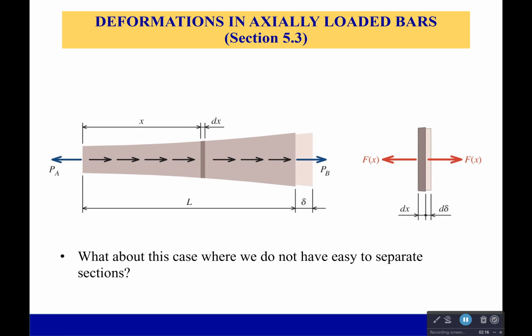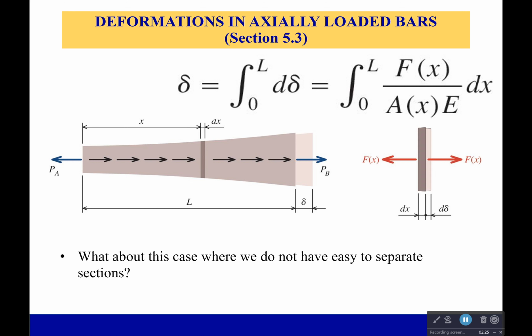In cases where we have a cross-section that is just increasing, not in nice little gradients, but as a function, well, then we'll have to do an integral. Our sum turns into an integral, where the modulus of elasticity is still constant, hopefully. We'll integrate from 0 to wherever we care about, and then we'll integrate the force over the area. In these cases, the integrals aren't usually terrible. We won't do too many of these kinds of problems. It's much more often for us to have the system of interconnected bars, like the previous example.